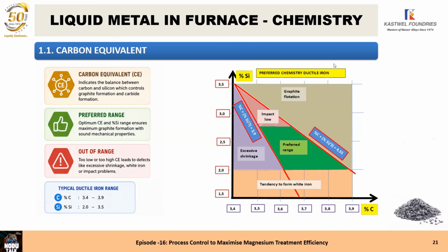Then comes the wire. You have to pay attention that a small wire in a big diameter ladle is not giving a good result, whatever your supplier will tell you about that. Then you need a double wire system or whatever to have a good result there. The advantage of the wire is that sometimes you can also put an inoculation wire in the system, and directly after the magnesium treatment, you can do the inoculation there. That's a very, very good system.